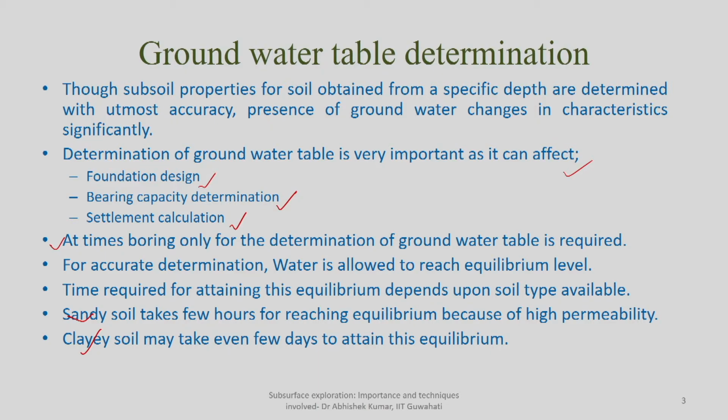Then, if you consider the soil above the actual groundwater table to be dry, which is actually not the condition, you are overestimating the strength of the material or soil, and the same will have an effect on bearing capacity and settlement determination.